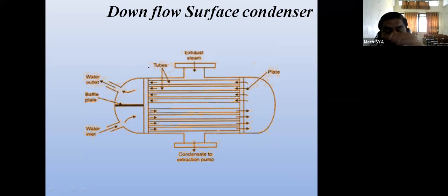In the ejector type, convergent and divergent cones are used to decrease and increase the pressure. Initially we decrease the pressure and increase the velocity for proper mixing, and at the end we use divergent cones so that the pressure at the end becomes more. But there is direct mixing.